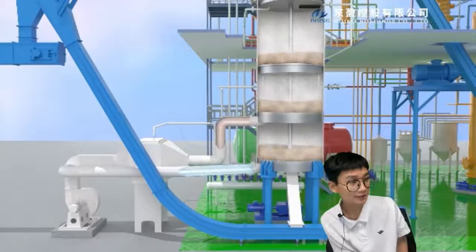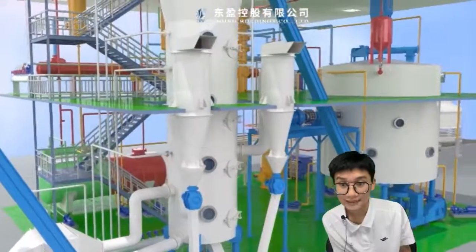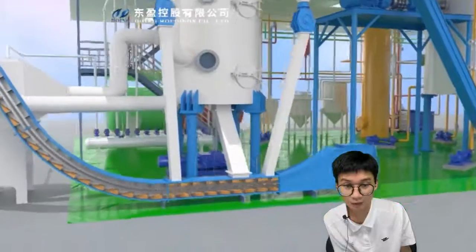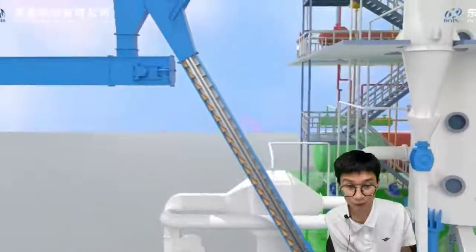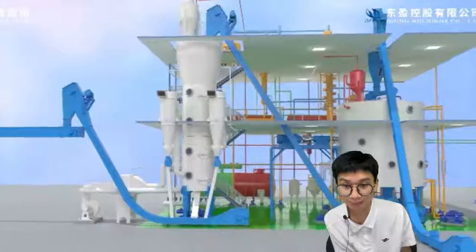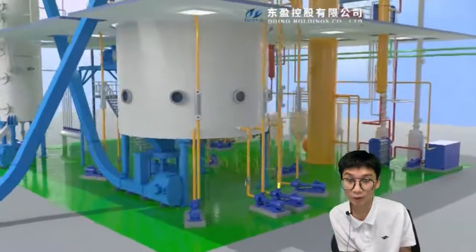And the last one, a really important factor, is the different machine cost. For the same input capacity, usually solvent extraction methods cost more than pressing methods, because a solvent extraction plant is an anti-explosion type workshop, which means all the pumps and electric motors inside the plant are anti-explosion type. So you can choose the different processing method according to your budget.